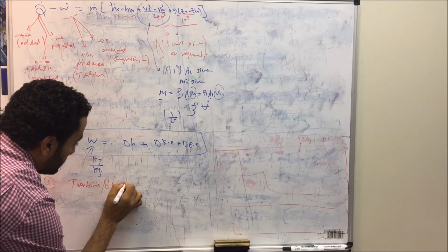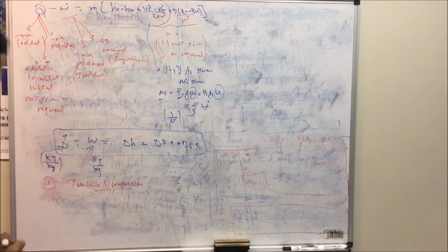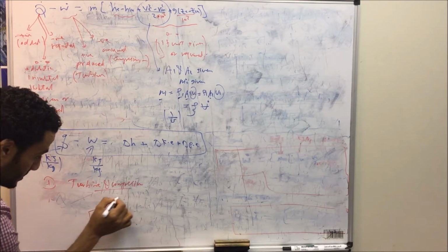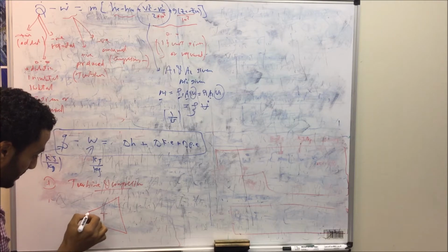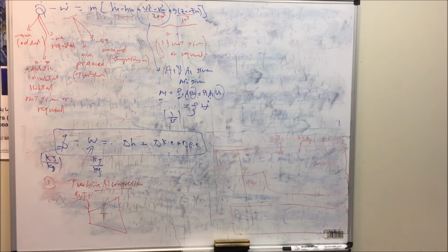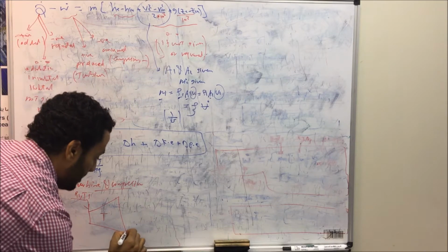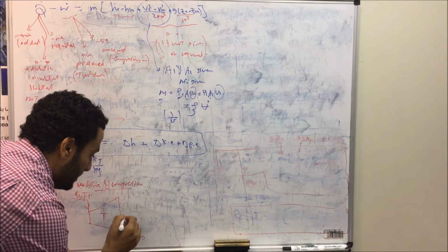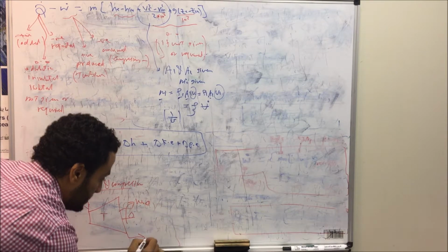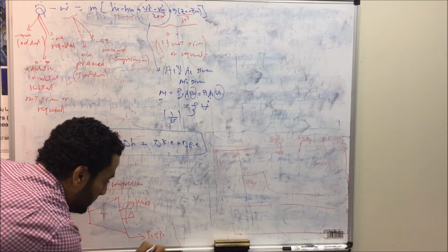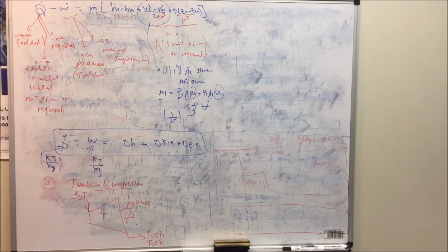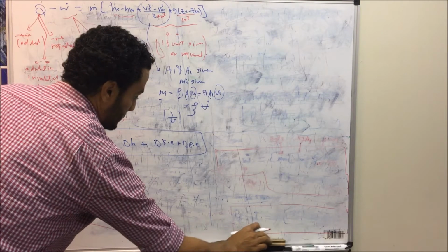and compressor. So in case of, let's say, turbines, we have an expansion process through the turbine. Usually the flow is coming to the turbine at pressure P1, temperature T1, which is high pressure and high temperature. And then the flow expands through the turbine to drive the shaft and then we can have work out of the system, and the flow is leaving at pressure P2 less than P1 and T2 is less than T1. So the process through the turbine is expansion.